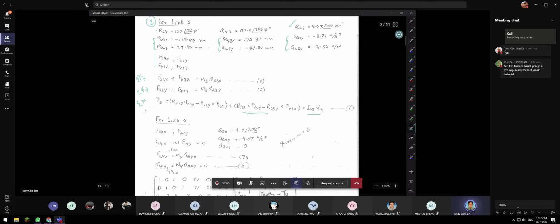Now you go to the next link, link number 4. Right, link number 4, we have to find this value F_x and F_1 rather than two value. Okay, we are given a_G. We have to find a_Gx and a_Gy. There's no a_Gy because it's 180 degrees, isn't it? All right, and we are also given mu is equal to 0.